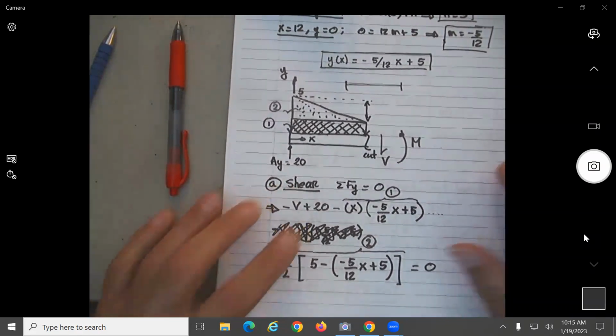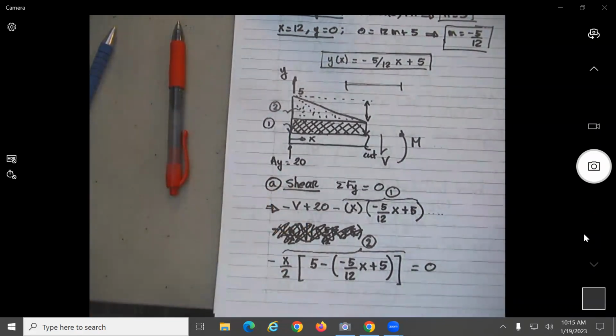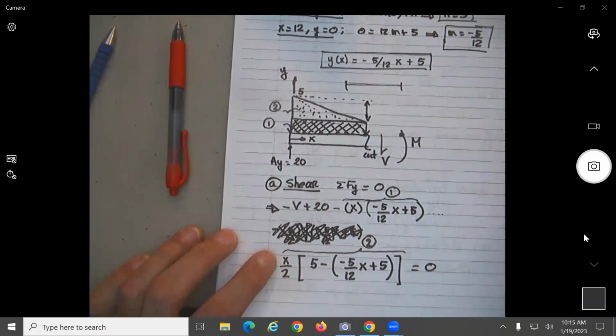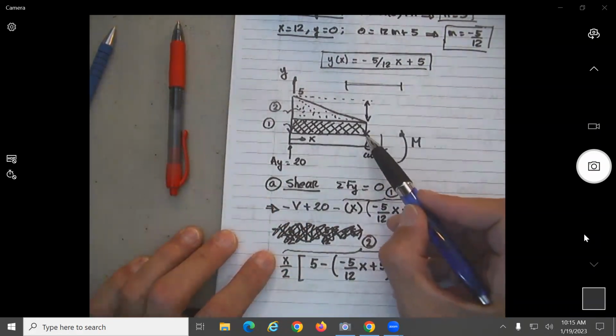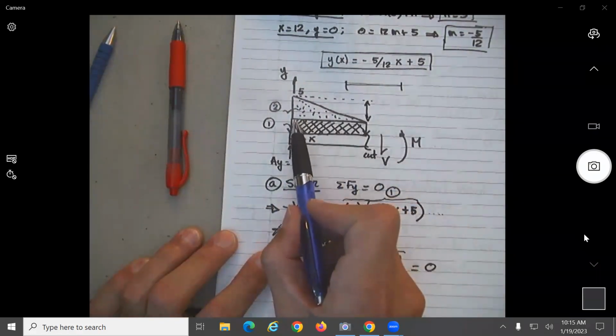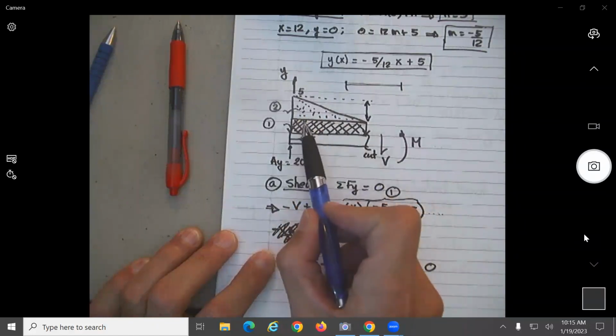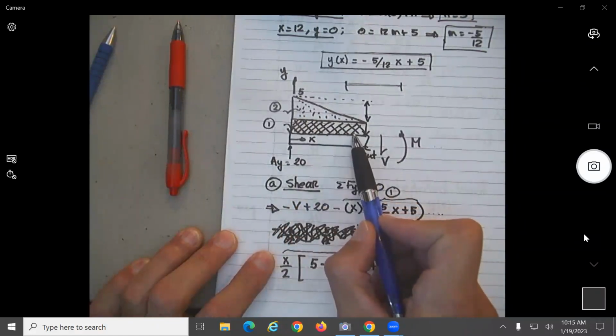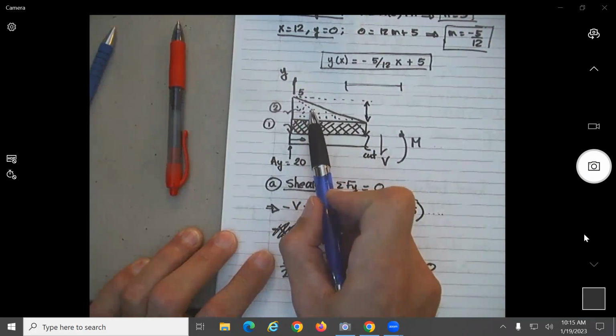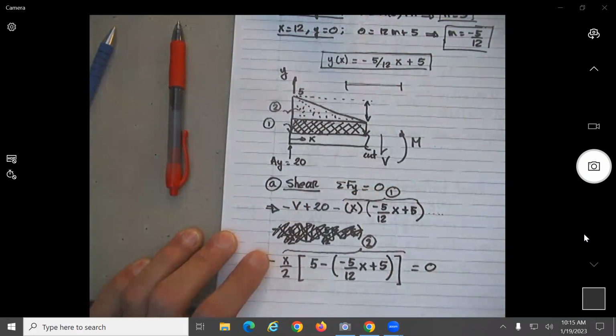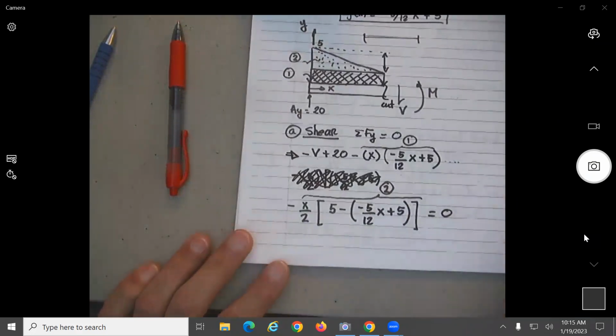So now, when you do the free body diagram from the end A, you see it's a lot more complicated. Because when you start from this end and you make the cut, what do you have? You're going to have one load which is rectangular over here, and one load that is triangular. But after that, basically we do the same procedure.